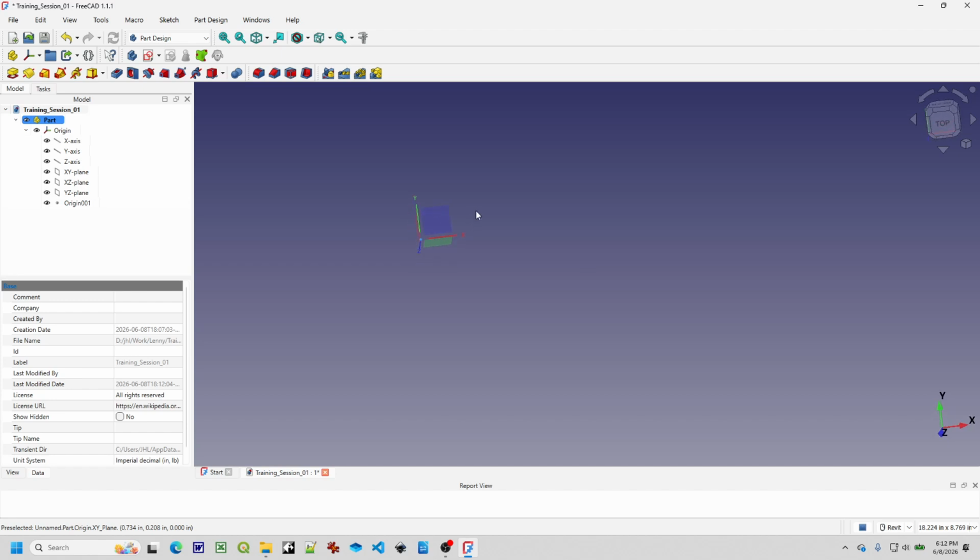I like to use a couple other things. There are options for which keyboard style you like as far as how you 3D rotate and pan. I use Revit because it's similar to what Autodesk Inventor uses, so I've just been using that one, but that's personal preference. Down here you can switch your units. You can work with units convenient to you, like 25.4 millimeters. If you switch to inches, it'll be 1 inch, so you don't have to rescale. It has engineering units built into it.